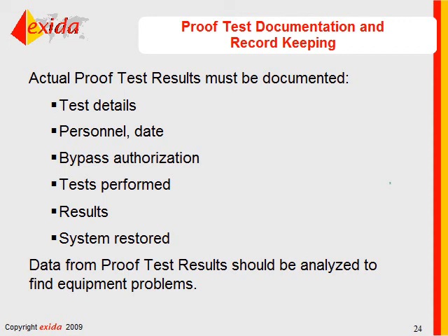Now, can you do it inline? Yes. Assuming that you have, let's say, a pressure transmitter before and a pressure transmitter after the valve, you can do some leak testing by just looking at the differentials there.